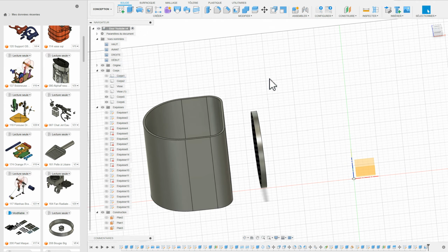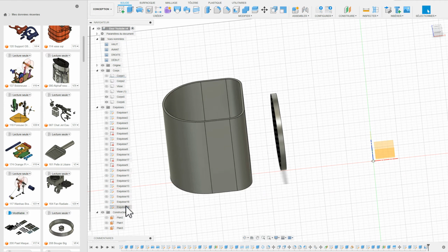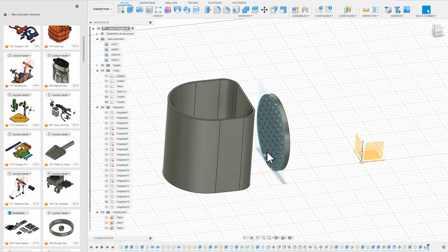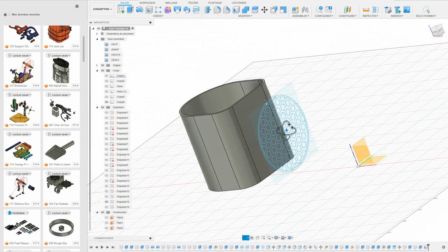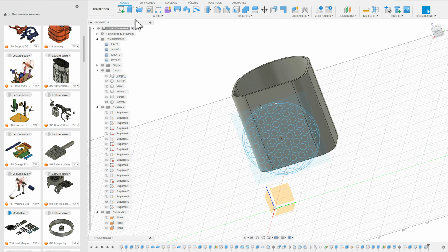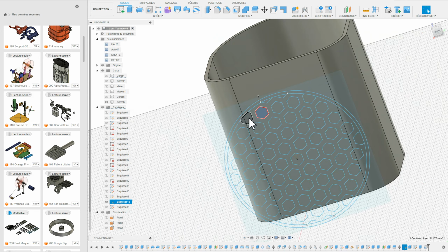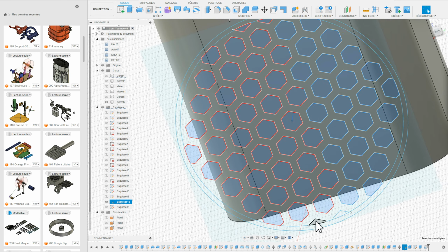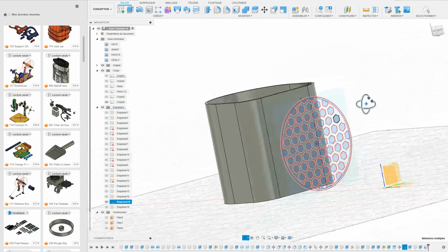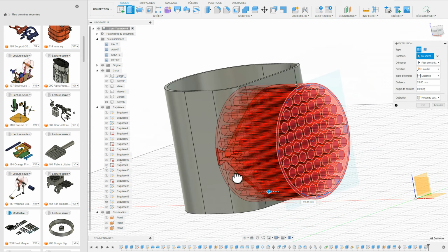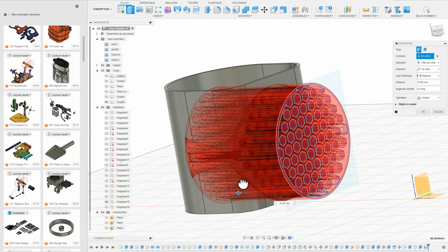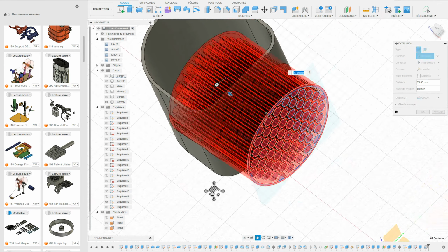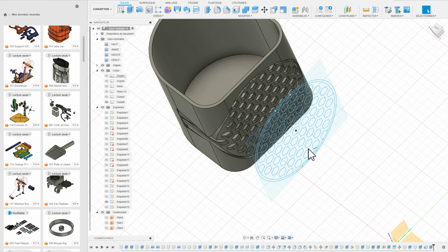I make the last sketch I want to work on reappear. This one? No, it's the second to last then. I don't need body 5, it's the sketch I need. So I'll reuse it to work on a new body. Just like earlier, I'll speed up the selection using the old sketch and the new body. I'll extrude and validate. That's what it looks like.